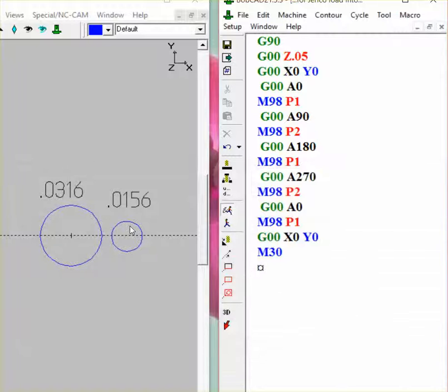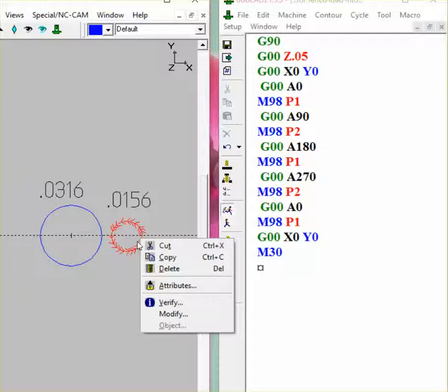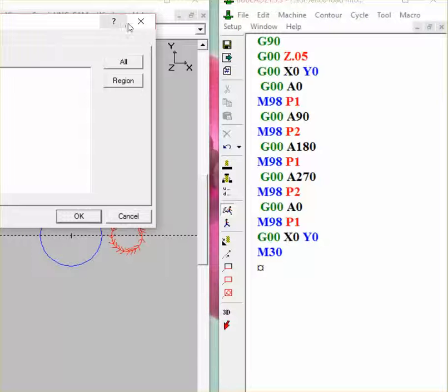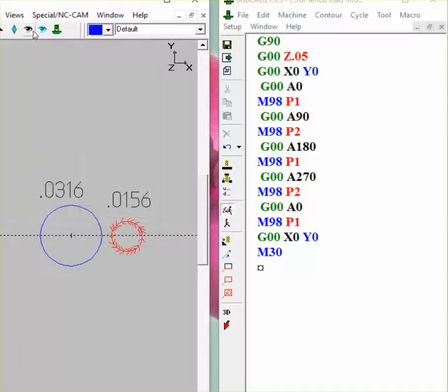So now what we're going to do is program this one right here first. Alright, you see where this one is. Excuse me. So what we need to do is we'll come up. I have that selected, and with that selected, what I'm going to do here is blank it, and you have your blank features up here, and this will blank the one that's selected, that one, so it won't write the program.